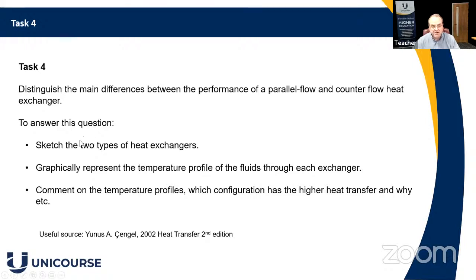So how would you answer this question? Well, the first thing would be to sketch the two types of heat exchangers. Physically, they look very similar, except the flows are in opposite directions. That's the only difference. Then graphically represent the temperature profile of the fluids as they flow through each heat exchanger.